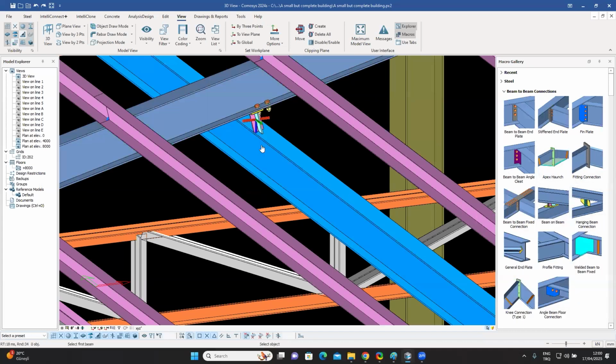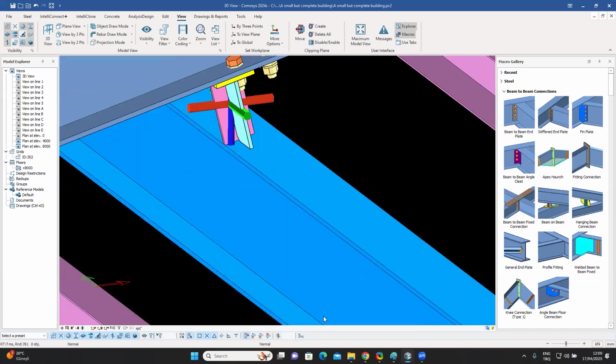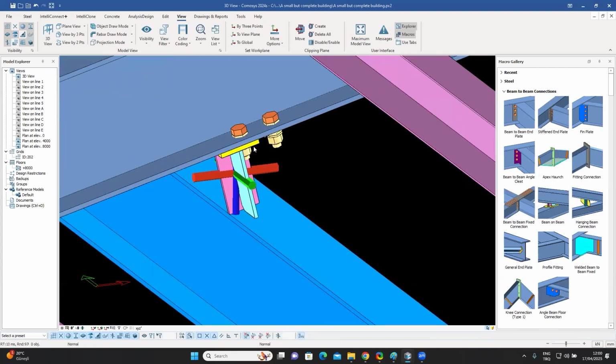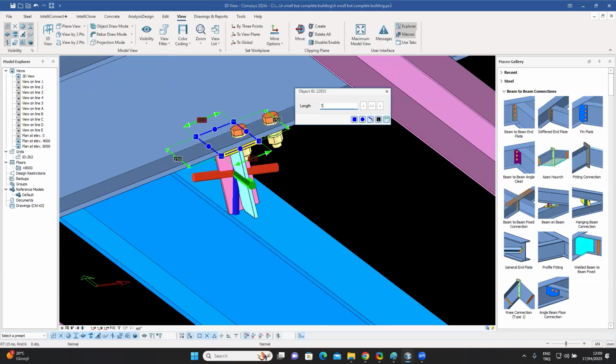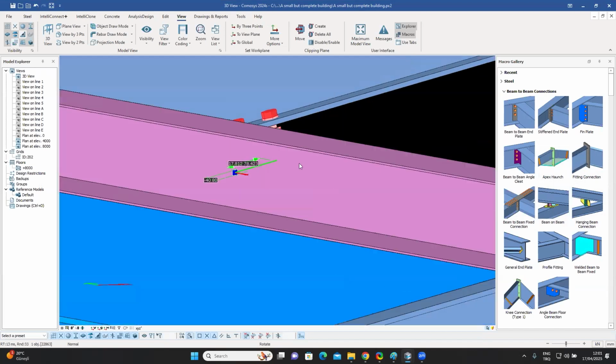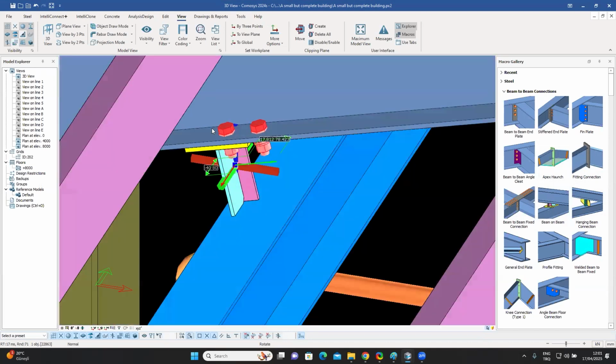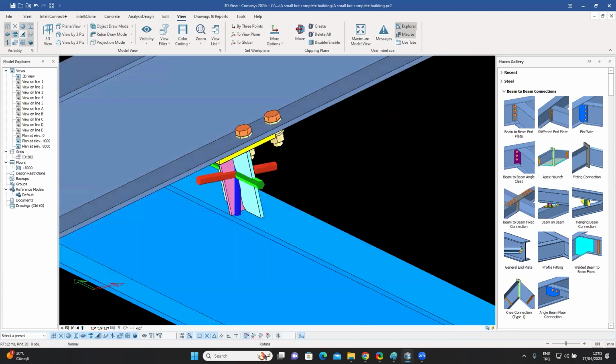But even then, if you notice that a particular macro is not working exactly as you wanted, it doesn't mean you need to do it entirely manually. What you could still do is use the handles to make your modifications. So, for example, I could select this plate, and instead of keeping them at 92, I could make them 150. Extend them on both sides, move the bolts if I wanted to, for example, basically any manual modification which you might need to do. What I could then do is maybe just select this area over here, say show only, so that it doesn't get in my way.